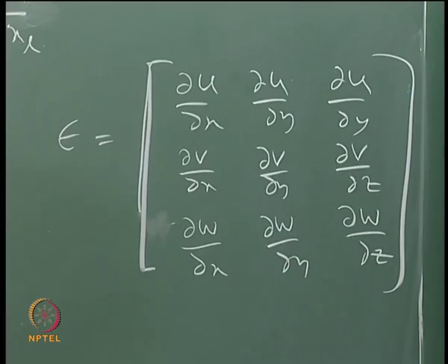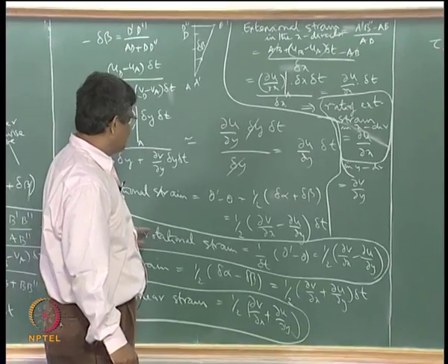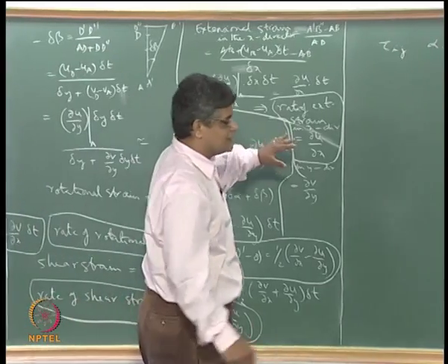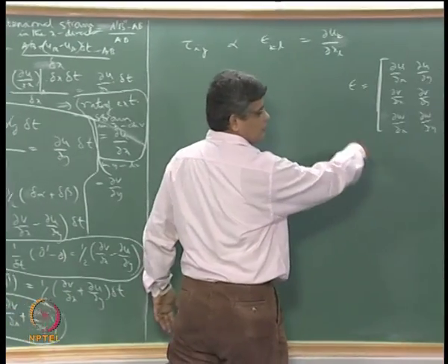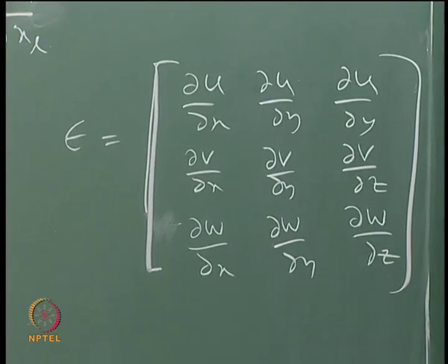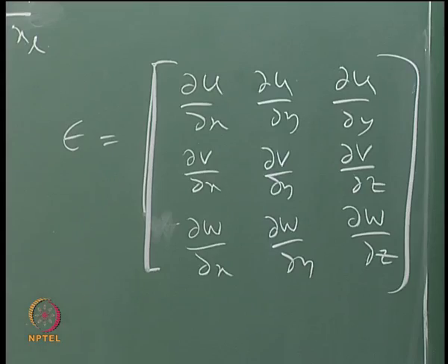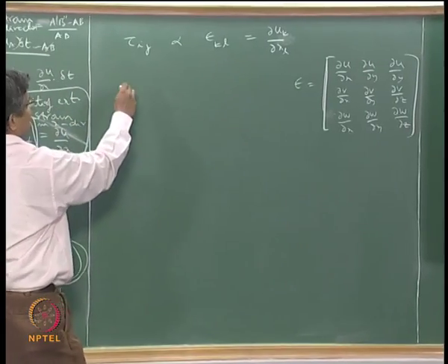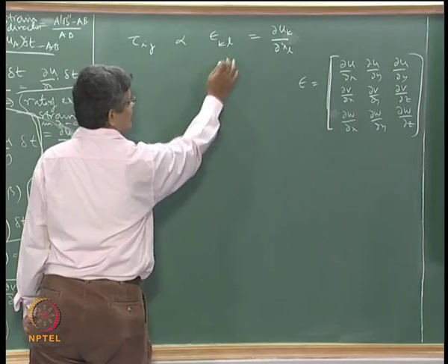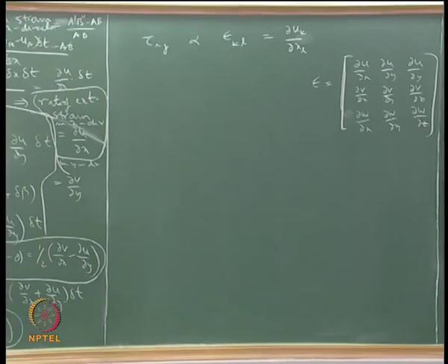These are all the different velocity gradients, okay, and different components of shear and strain and shear, rotation and extension are different combinations of these velocity gradients. So we put everything here together and we make a linear relation between the shear stress, the viscous stress and the strain rate as a general expression.